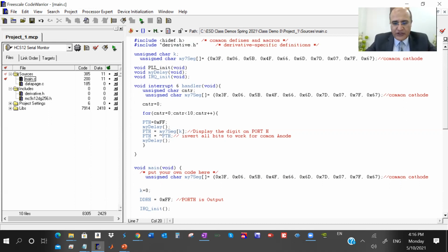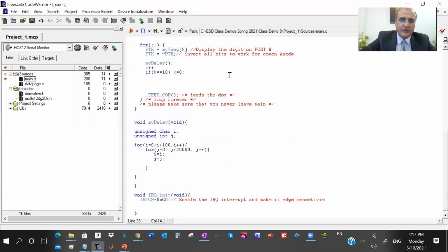Let's initialize it at 48. Do you want to make it variable? You pass a variable at a certain frequency. You can, of course, do that. So I'm going to write the PLL init. I run it immediately after entering my microcontroller, for example here. PLL underscore init, I just call it. And down here, we write the code.